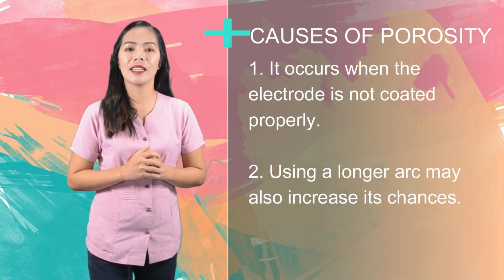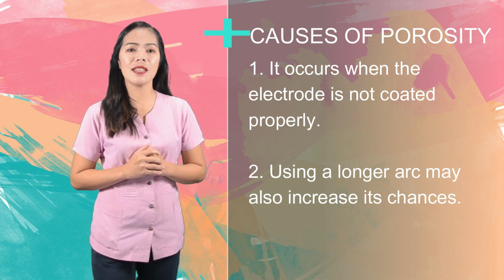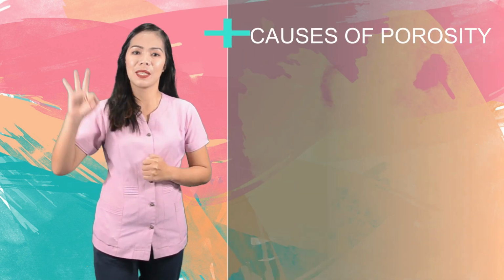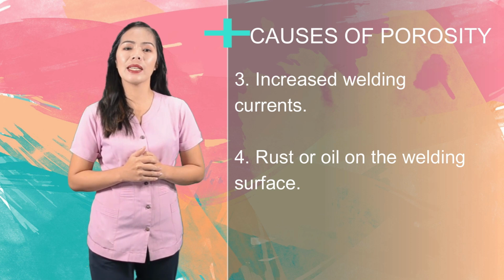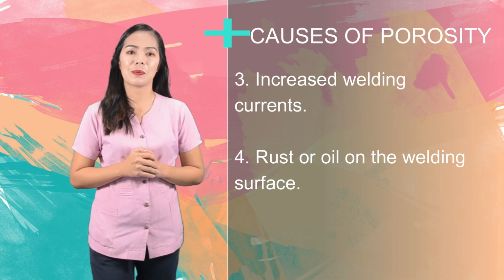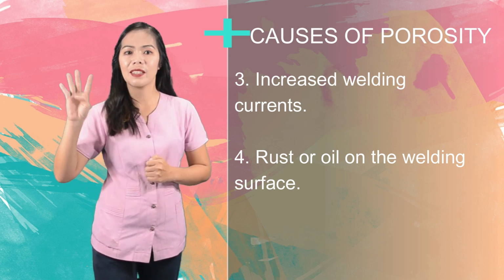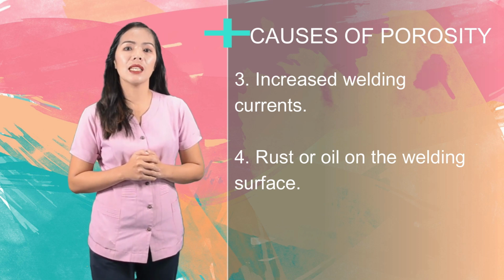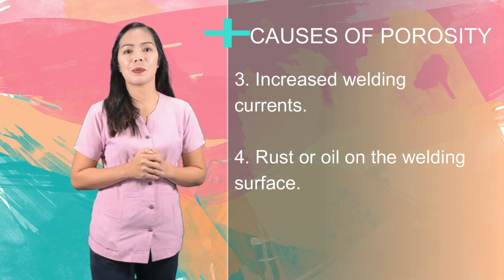Using a longer arc may also increase its chances. Number 3. Increase the welding currents. Number 4. Rust or oil on the welding surface.